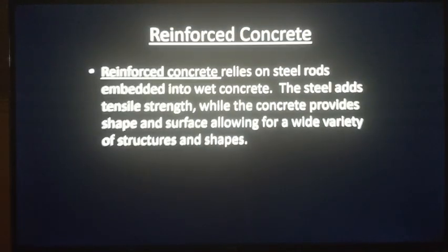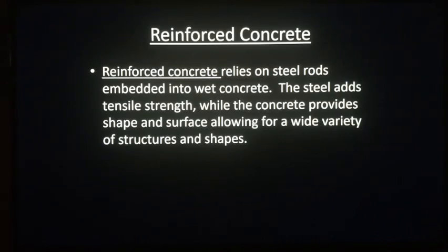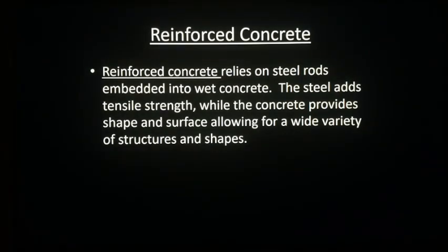Reinforced concrete is one more of the innovations that we see revolutionize construction in the 20th century and now into the 21st. Concrete has been used for construction since the time of the Romans, even in the Pont du Gard that we looked at earlier, that was constructed in Nimes, France, as a viaduct and an aqueduct. It's a very strong material, but it doesn't have very much tensile strength. When you add steel structure underneath in the form of rebar, this adds a lot of tensile strength, and we can increase the distance that concrete can span without breaking.